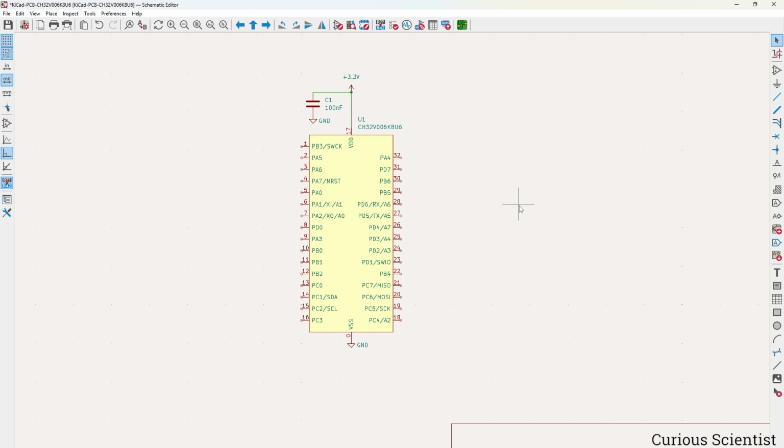And now we have to do another tedious task, at least I want to do that now. You can see that we have all these pins, but they don't go anywhere. In order to avoid clutter, when we wire something, I don't want to just run the wire across the whole drawing. I will put a label on each of these pins according to the names here that we can see.